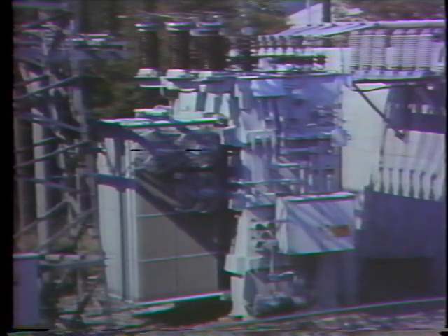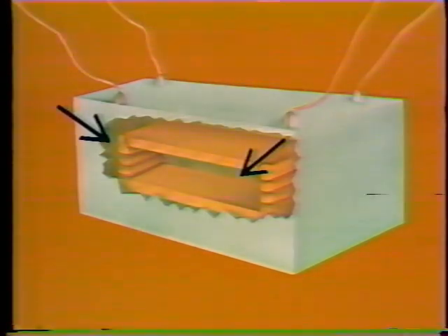Before we leave the subject of transformers, there's one more area I'd like to cover very briefly. Transformer cooling. Most electrical equipment heats up as it works, and some means must be found to keep it from overheating. Many transformers, particularly the smaller ones, are cooled by the air around them. With some larger transformers, however, air cannot provide adequate cooling. Most large transformers are filled with a liquid, such as mineral oil or a solution of liquid chemicals.